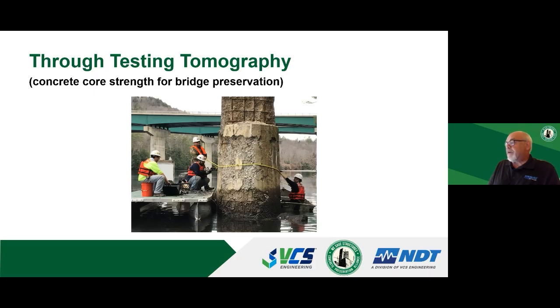And we determined that the overall compressive strength of the internal concrete, the core strength, was over 5,000 PSI. The outside was 900 PSI, or we didn't even get readings in some areas because it was so deteriorated.